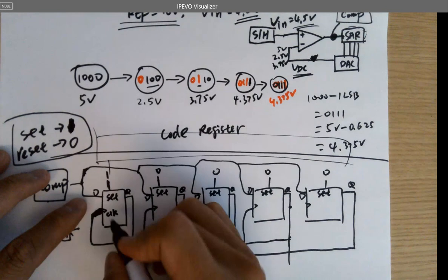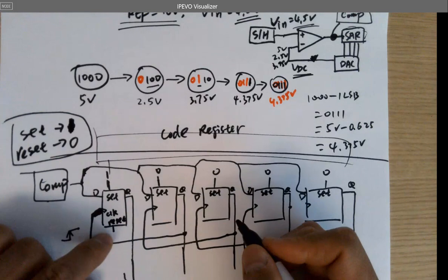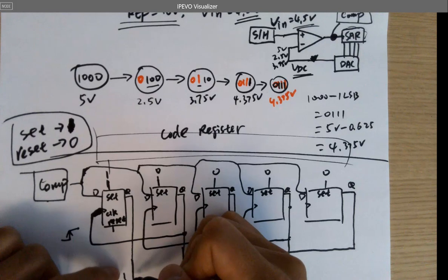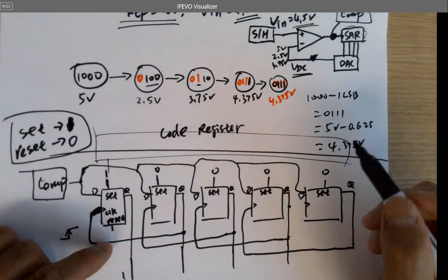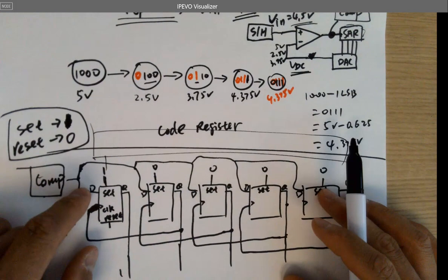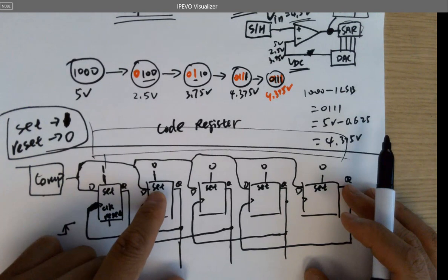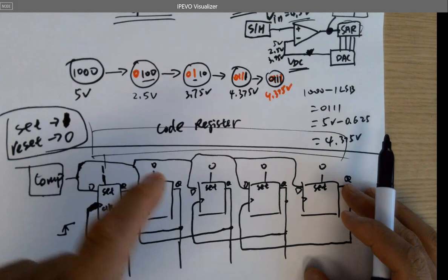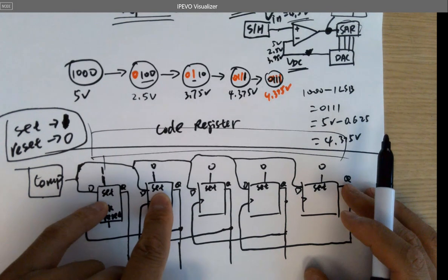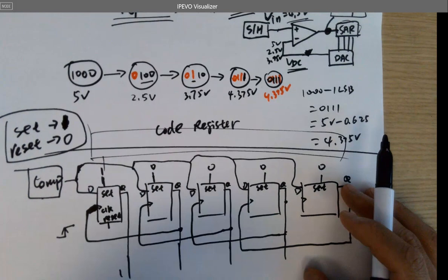And there might be a reset pin as well, right? You can have a reset pin as well. Whenever you give a 1 here, it's going to reset your Q, which will output a 0. But we are not using that reset right now, just using a set. So set is going to set it to 1 no matter how D changes. Remember that. So 0 sent to set is not going to change anything. If you put a 0 to set, you didn't turn on the set function, you release that D flip-flop, so it's going to behave like a D flip-flop.